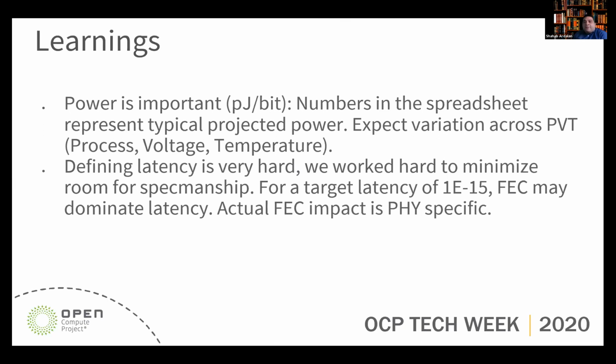I think that can immediately define two different categories: you go to the silicon interposer or the organic interposer type of PHY. And after that, it comes down to a couple of other things. For example, do you need latency or not, do you want to be unidirectional, or is your link fully symmetric, or is it 90% of the time in one direction. These are more on the architecture side rather than just picking one and saying, oh, this is the best compared to the others.